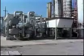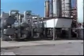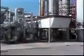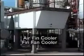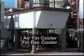To get a better understanding of how heat transfer occurs in a heat exchanger, we'll use this heat exchanger. It's called an air fin cooler, or a fin fan cooler. It's used to transfer heat from a process fluid to the air that flows through the cooler. The cooler consists of a series of tubes, each of which has thin metal fins. The heat exchanger also has a fan. During operation, the fluid being cooled passes through the tubes.